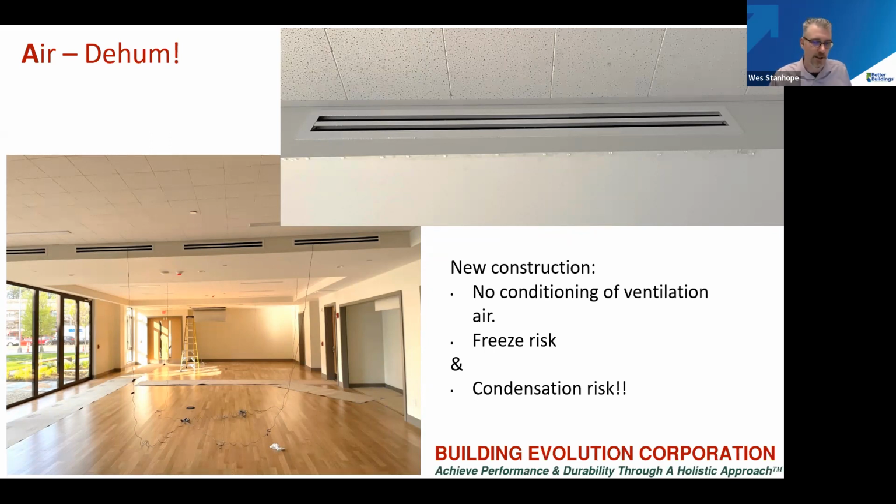This is an example of a building that was constructed without conditioning of the ventilation air here in the Northeast. We were called in to review what was going on. Well, we knew what was going on, but we did an assessment just to confirm it. The moisture-laden air is hitting dew point and condensing on all the surfaces. It is key to dehumidify the air when we get to high performance, and the systems need to tackle that at the source, at the ERV, with a high efficiency ERV to tackle that load. Next slide.